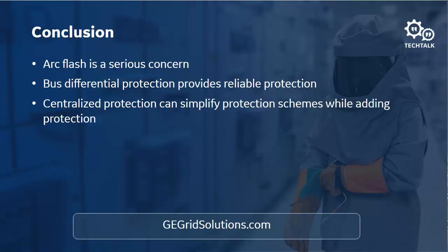So it can give you some flexibility, without having to upgrade all your feeder relays, just doing a transformer relay with arc flash protection and routing those point sensors appropriately to give you that protection. So it sort of depends. We can talk about that later.